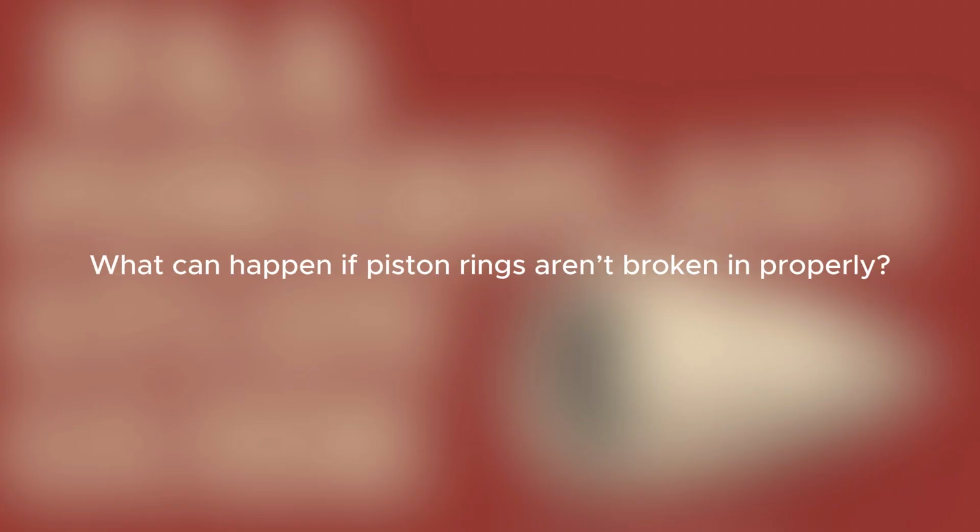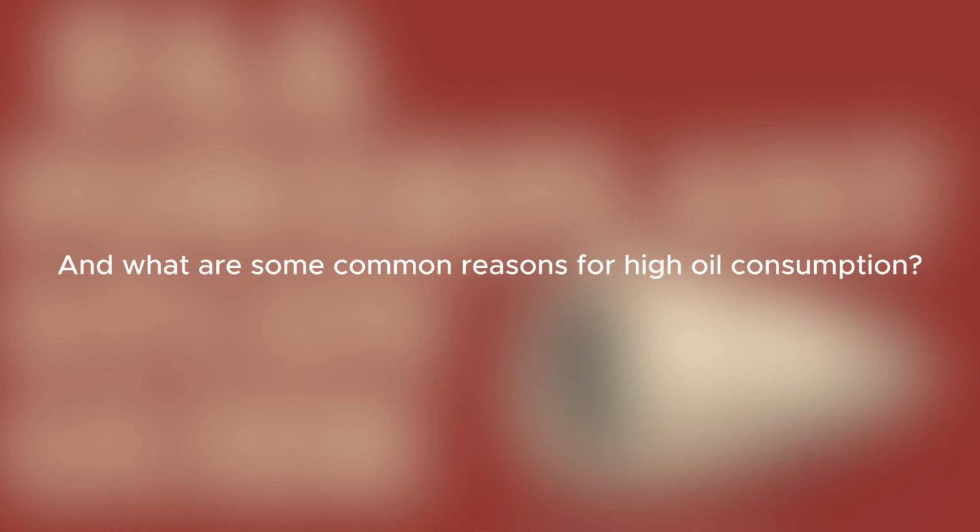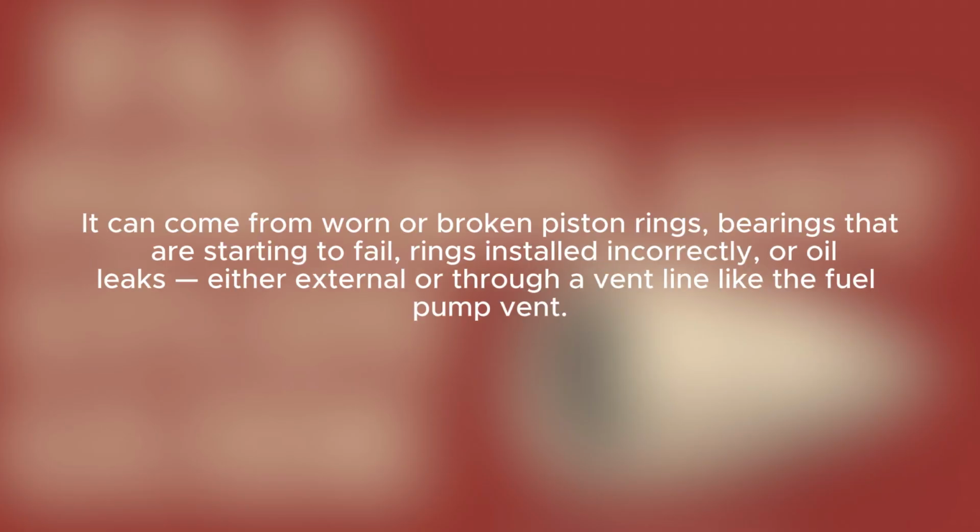What can happen if piston rings aren't broken in properly? Poor break-in can cause the engine to use too much oil because the rings never seat correctly. And what are some common reasons for high oil consumption? It can come from worn or broken piston rings, bearings that are starting to fail, rings installed incorrectly, or oil leaks, either external or through a vent line like the fuel pump vent.